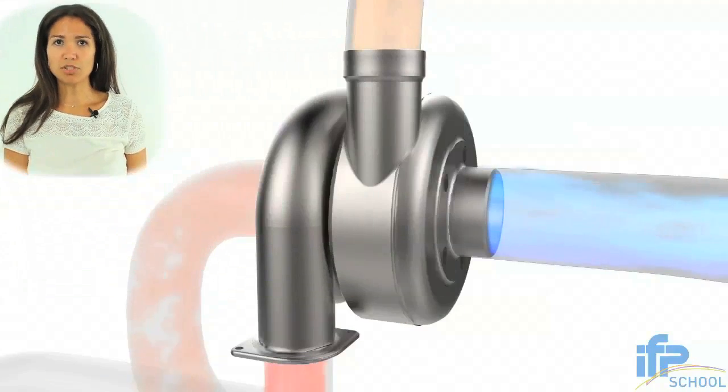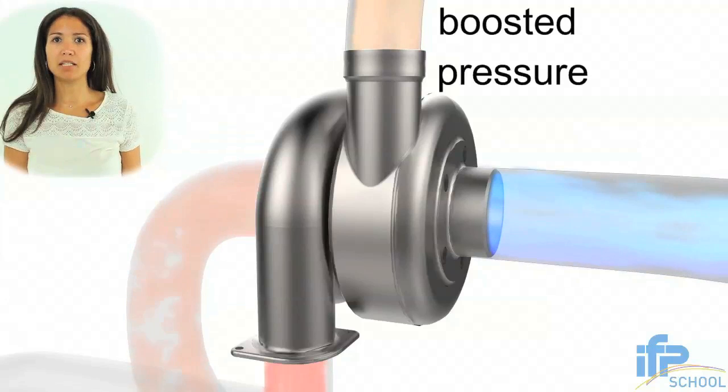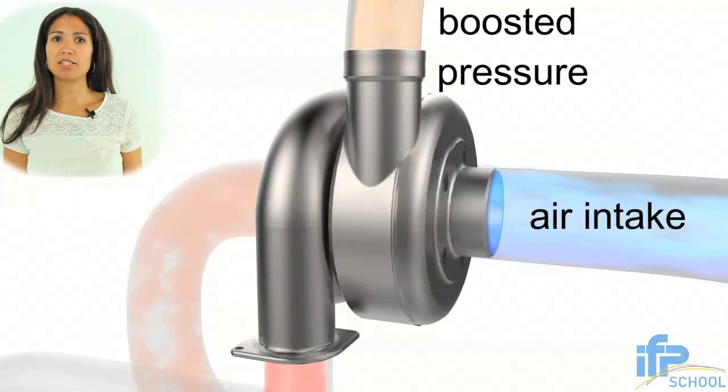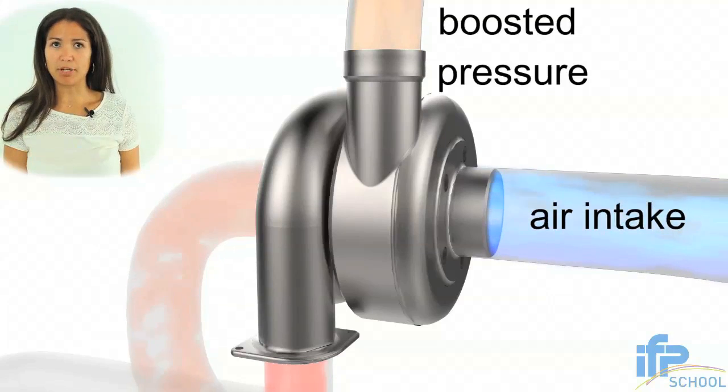In naturally aspirated engines, fresh air is drawn into the cylinder directly from the surrounding environment. Nowadays, most of the engines are equipped with a turbocharger, since this means the power of the engine can be considerably increased. The turbocharger increases the air pressure so a higher mass of air can be inducted by the engine for each engine cycle. In this way, a higher quantity of fuel can be burned.